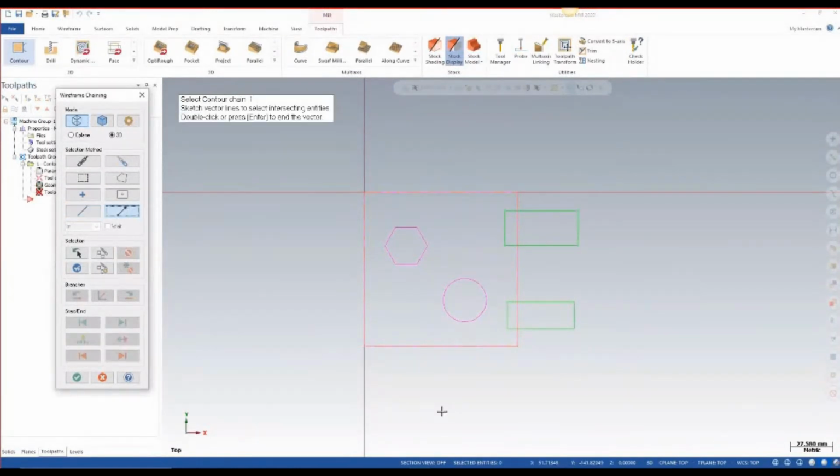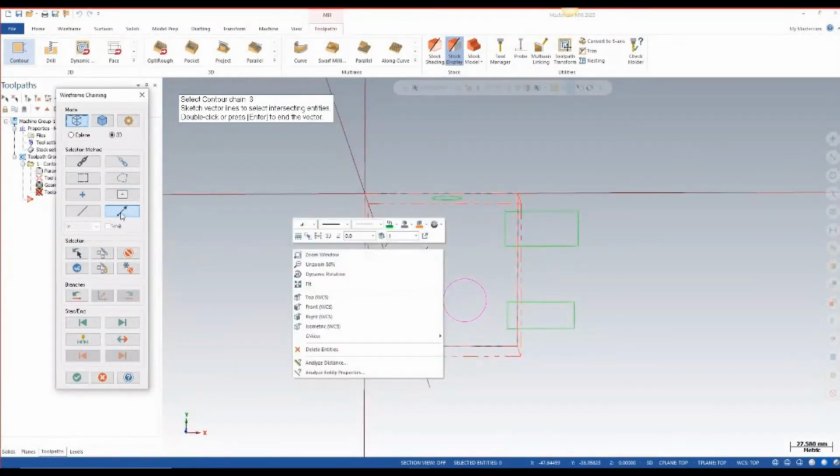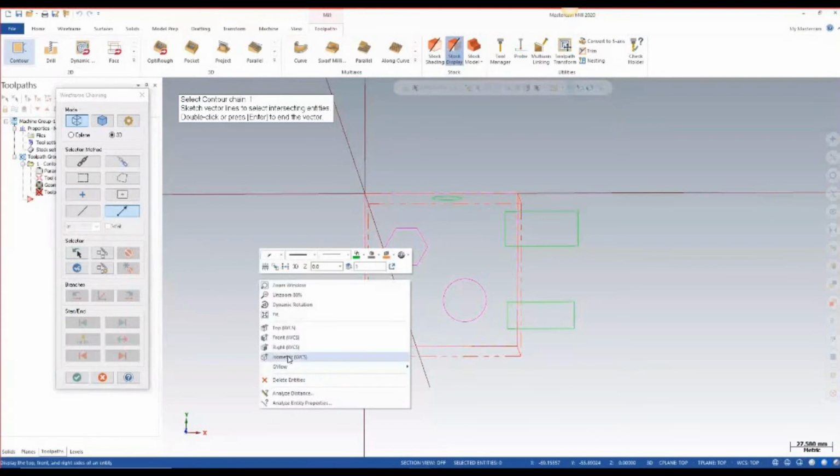And vector. So when you drag a line and say enter, whatever the line you are creating intersects, any wireframe, that gets selected. That is about vector. So this is about my selection method, and here we have a few selection options which will be very useful.